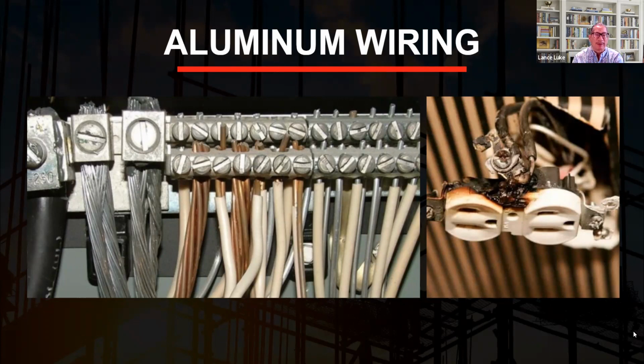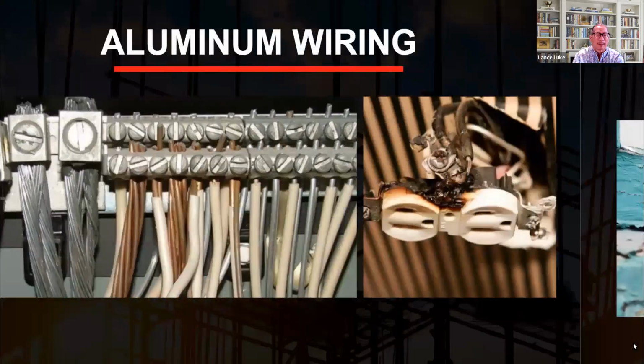Sometimes in the photo on the left, this is a circuit breaker panel that's a ground bus bar. And if you see the copper wiring and then on the right aluminum, that's not a very good situation because aluminum and copper are dissimilar metals and it's subject to corrosion. So eventually all these screw terminals are going to get corroded, and then the connection is going to be not 100%, which is not a very good situation for electrical in the house. Okay, so corrosion is another factor in aluminum wiring.